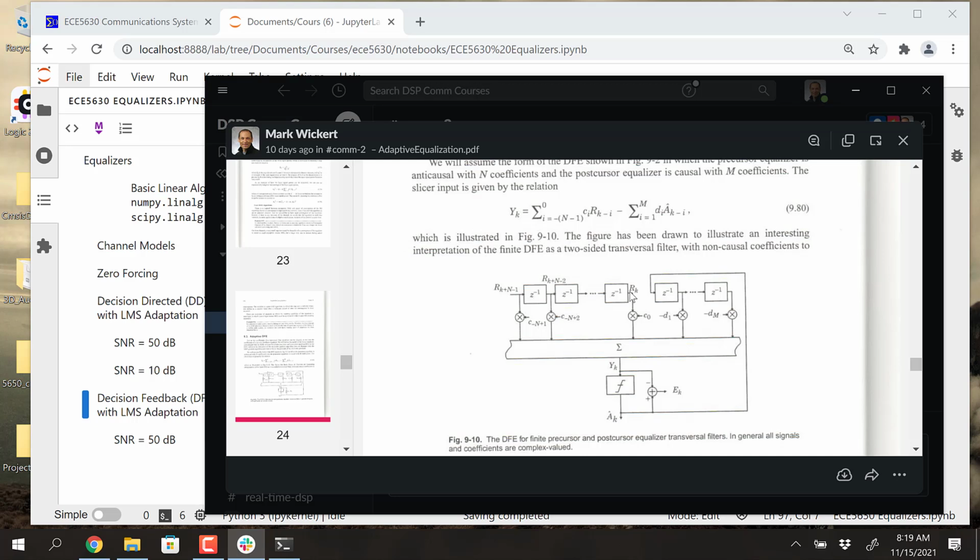With the LMS, yeah. LFilter can be used for an adaptive filter, but LFilter works best for a time invariant system where the coefficients get loaded in and they don't change. With an adaptive filter, they're changing at every step. So LFilter can be used. It's just that you're going to have to reload coefficients every time into it and then take out the states, and all that stuff. I've done it that way too. My DSP class may be doing adaptive filters for noise canceling in their final project, and I give that as one of the options that can be done.